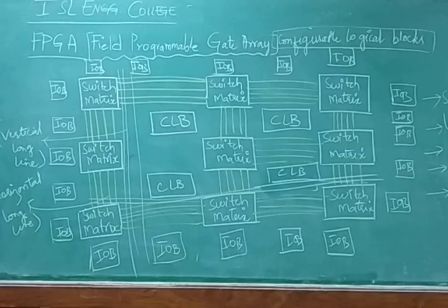Make a note of it. And when you want to see the CLB, the main thing would be the interconnect resources, means how you are going to give the connection to these particular resources. That is going to be the important part while designing this FPGA architecture. Each programmable IO pin has programmable IO with compatibility for different logic levels. What is the meaning of this?